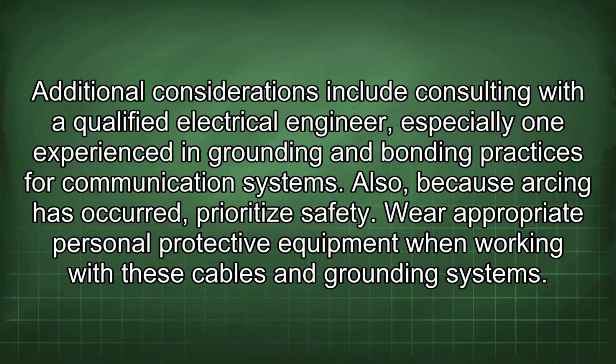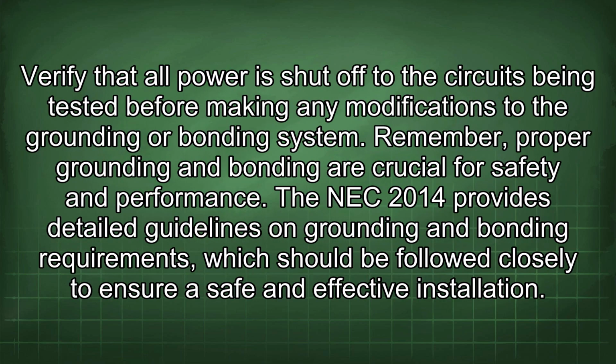Also, because arcing has occurred, prioritize safety. Wear appropriate personal protective equipment when working with these cables and grounding systems. Verify that all power is shut off to the circuits being tested before making any modifications to the grounding or bonding system. Remember, proper grounding and bonding are crucial for safety and performance.